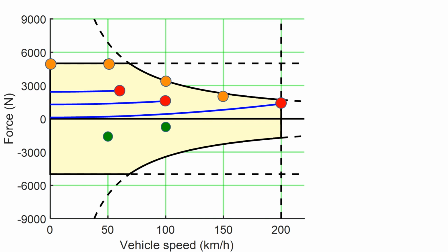These are the required operating points for the vehicle in our example. We only need to meet the most demanding of the positive and the negative battery power requirements respectively. But since the efficiency varies with operating point, we cannot be sure it's the requirement with the highest traction power that will lead to the highest battery power, even though this is actually often the case. So it makes sense to at least analyze the requirements with the traction power close to the one with the highest traction power. For the operating points with a high traction power, we calculate the battery power as the traction power divided by the total efficiency of the electric drive system.